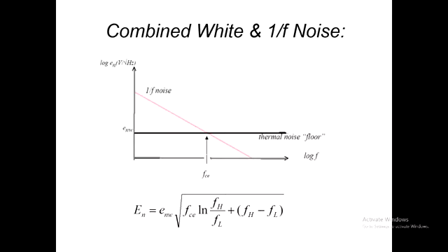Yeah. Are the upper and lower frequencies on that graph the same for pink noise and white noise? No, what we're actually saying here is that if we take a slice, if we have a particular bandwidth of interest, we might have a device that works up here, say, this is the low end of the bandwidth and this is the high end of the bandwidth. Then calculation for that's a cinch. We just take the high minus low and multiply by the white noise level. And that's what you see here.